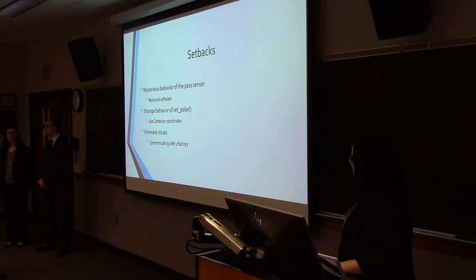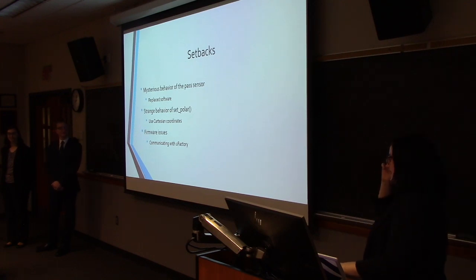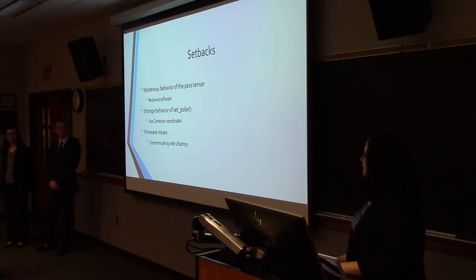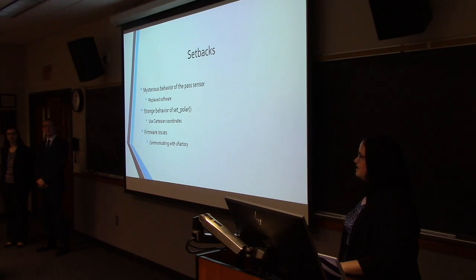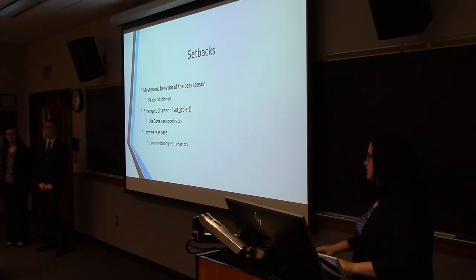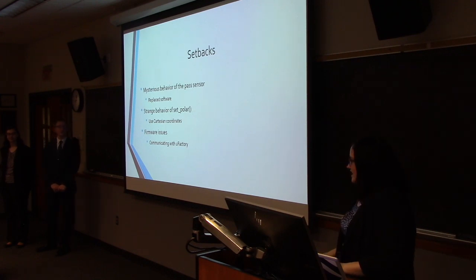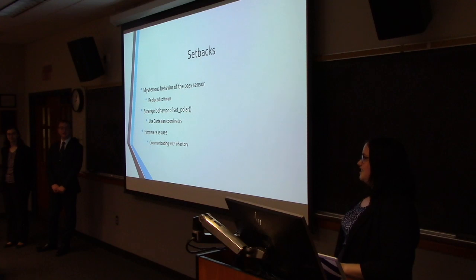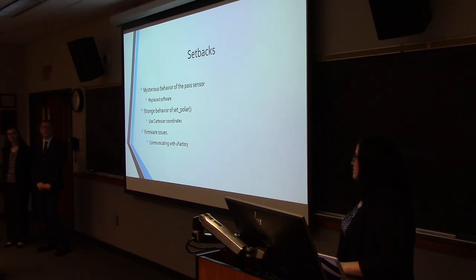The last issue we ran into, which we ran into like last week, was a firmware issue. The U-Factory updated the firmware, and this firmware claimed to be faster and better and just all over great. We updated it, and it slowed our robot down. It took about 5 seconds for any of the motion commands to load, and it would time out before it even got there.